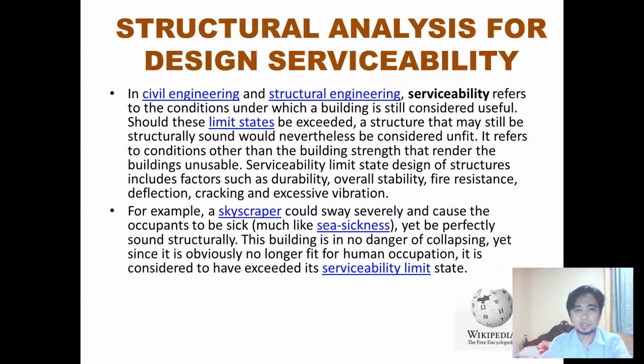For example, a skyscraper could sway severely and cause the occupants to be sick, much like seasickness, yet be perfectly sound structurally. This building is in no danger of collapsing, yet since it is obviously no longer fit for human occupation, it is considered to have exceeded its serviceability limit state.